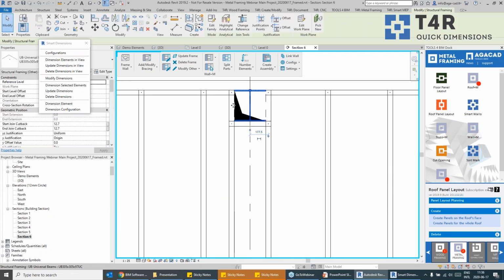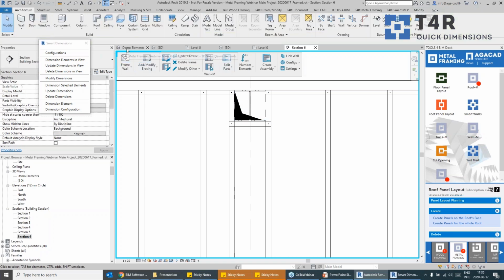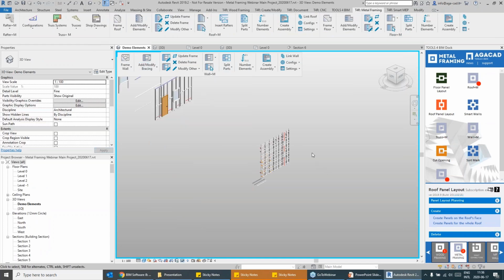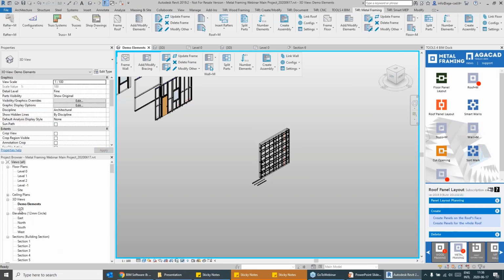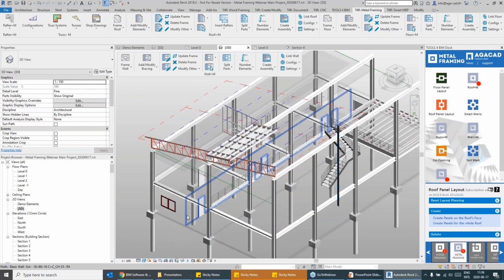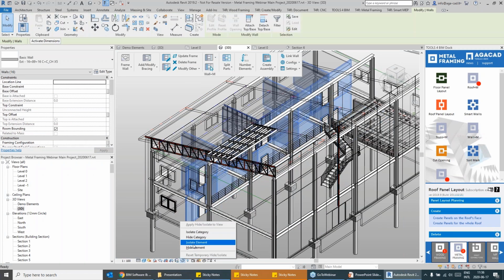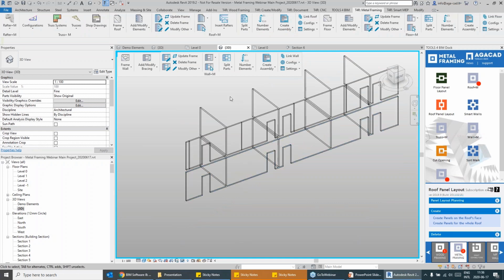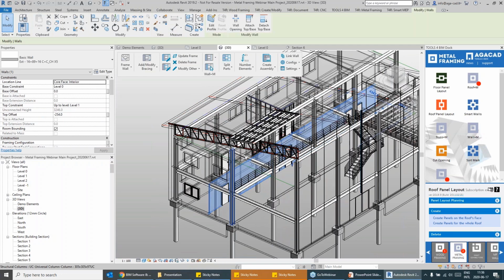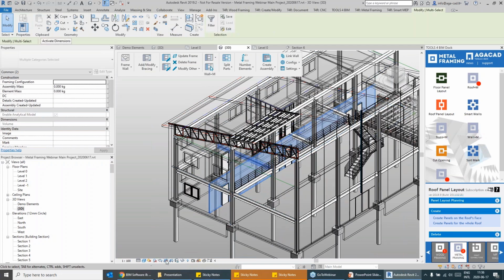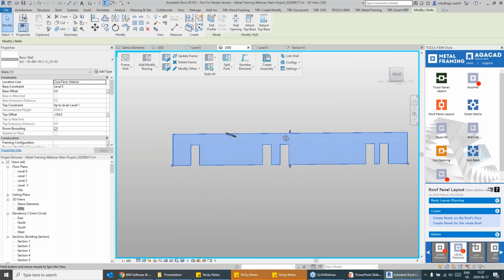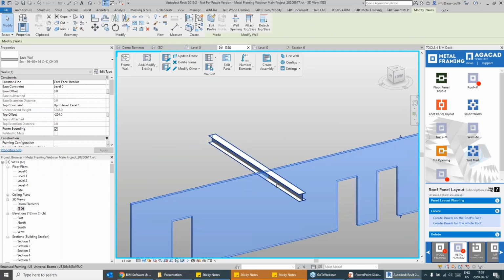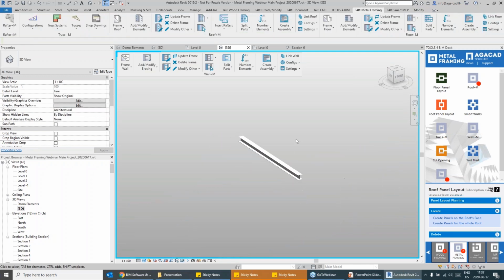And by the way, notice that I'm having here openings that I unfortunately forgot to show you how those were inserted. So let's go back to that model, which doesn't have openings yet. So if you go back to those walls, you can see those do not have any openings where my beams are intersecting them. So if you just take, let's say, that wall, and I don't know, that beam, you will see that there are a lot of conditions where my beams are intersecting my walls. So maybe I'd like to frame them around those openings.